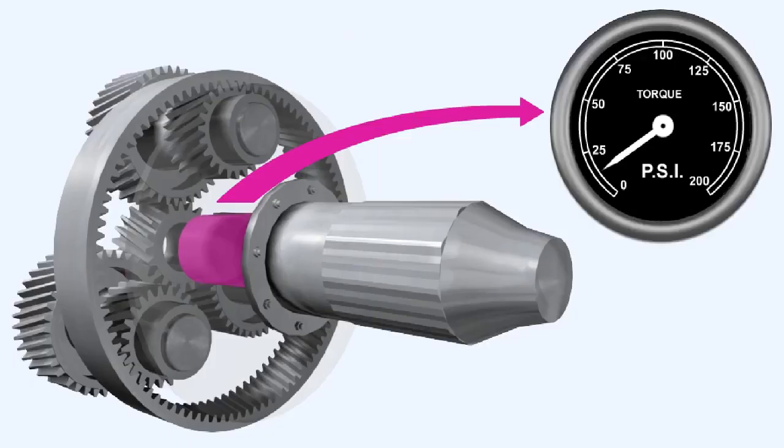To reduce the workload on the pilot in the event of an engine failure, some propellers are equipped with an auto-feather system. The system is normally active during takeoff and cruise conditions only. For example, on a turboprop engine, with the high-pressure fuel cock open and the power lever set to high power, a signal of low torque from the engine torque meter system will automatically feather the propeller. Should either of these conditions not be met, the auto-feather system will be rendered inactive.